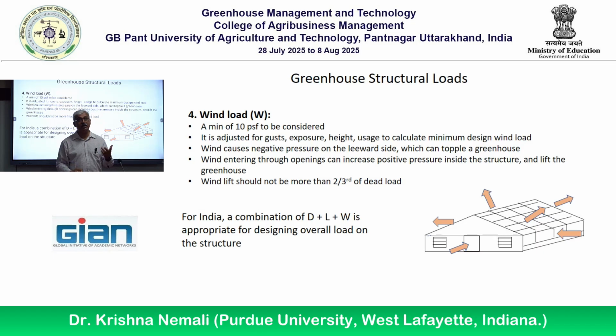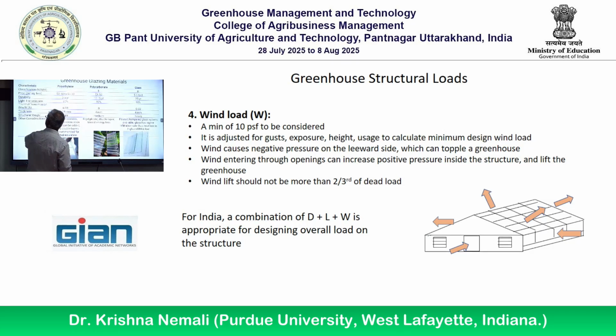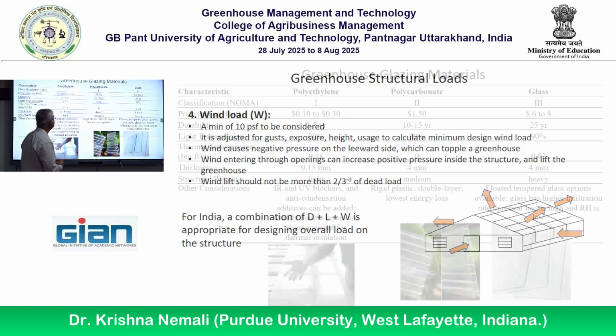If he comes and says dead load and you don't know anything about it, you say, okay, very good. He comes and says the dead load is 1 psf. Oh, very nice. But now you know it's less. It should be at least 5. Okay? All right, that makes sense, this overall load thing. I think there's one last section I should be able to finish in 5-6 minutes, or less than that.